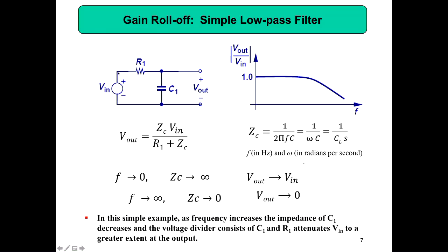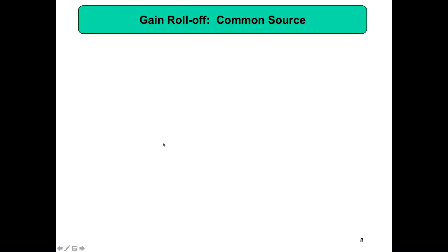So when the frequency increases, what is happening? The signal passes through R1 and comes here, but it does not go to this point. Then where is it going? The capacitor shorts all the high frequency components to the ground.